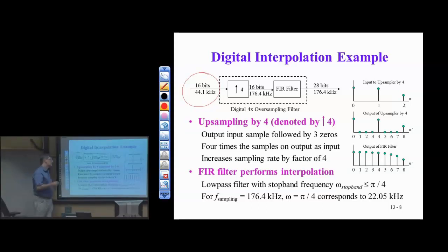Okay, so in this particular case, and we'll see why this is important when we do data conversion in lecture 10, this is a way that we can go to a higher sampling rate, which gives us oversampling for free. Well, not for free, almost for free. A little bit of complexity to do it, but we get a little bit of oversampling as a result. And we know oversampling is a good thing for lots of reasons. One of those reasons is that in data conversion we're going to, surprisingly, inject noise to improve the signal quality. And this gives us some place to put things like quantization error, noise we inject, into frequencies we can't hear.